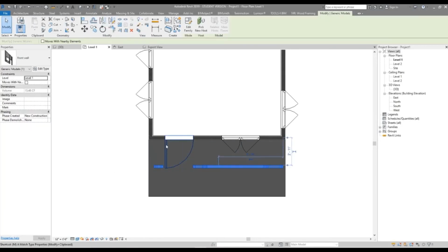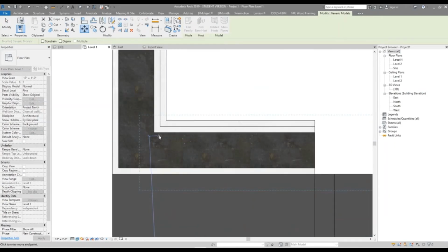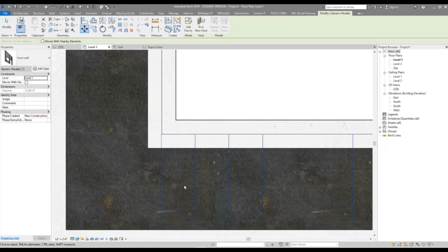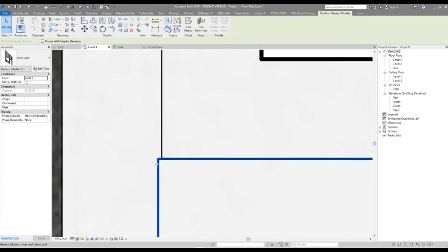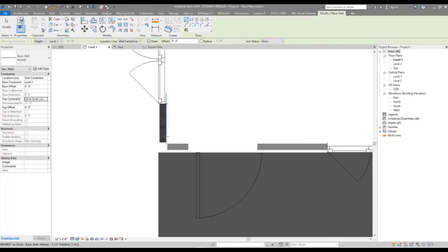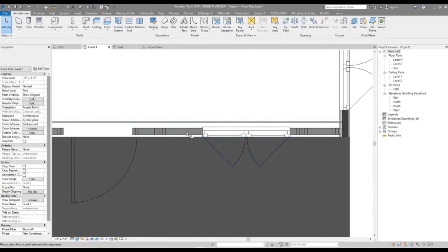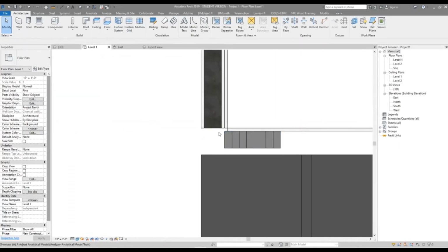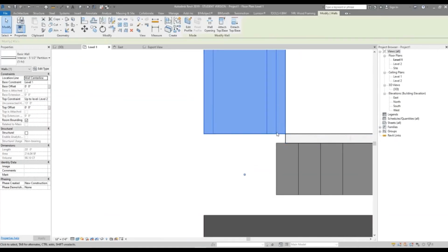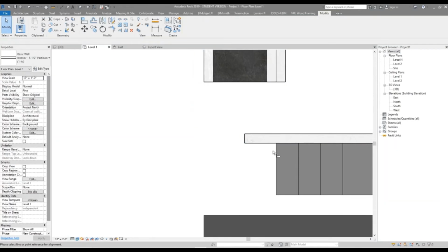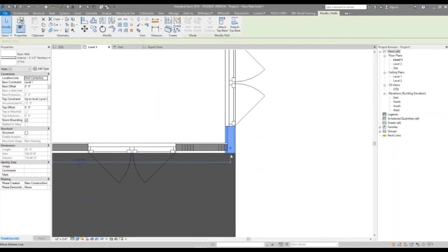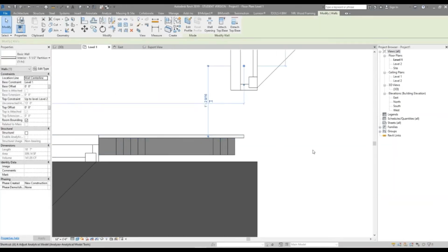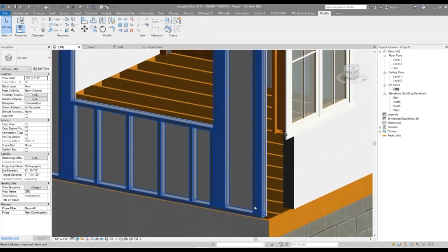After modeling the families, they were all painstakingly added to the template model in Revit and placed in the correct location. At this point in the process, the single explodable wall is fully modeled, and what is left to be done is the wall and floor coverings for the rest of the house. To do this, thin individual walls and floors were added from the built-in Revit tools. Special care was taken to make sure that the materials were set correctly and that clear naming conventions were used throughout for clarity.